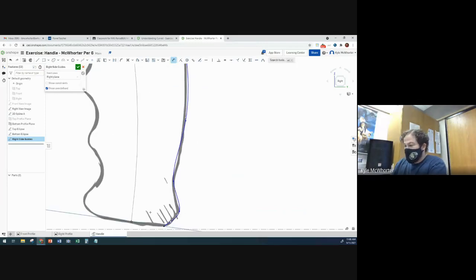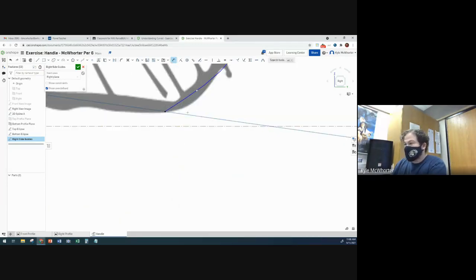And then for the bottom one, it doesn't want to give me the spline handle. So I'm going to get out of my dimension tool, drag this over a little bit, then get my dimension tool back, select that handle and the horizontal construction line, and that angle is supposed to be 25 degrees.